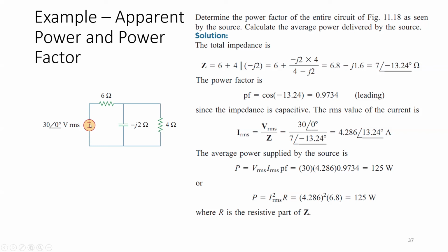So this means that the whole of the power delivered by the source is consumed across the resistive part. There is no power dissipated across the reactive parts in ideal scenarios, and that energy is moving to and fro. The power dissipation in the reactive part is 0, and we are going to see this in due detail shortly.